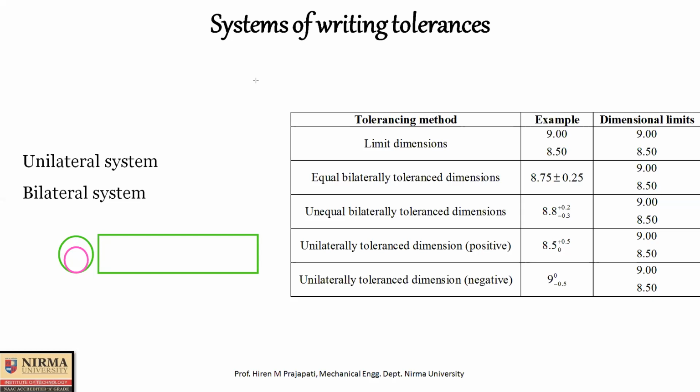Now in side view, if I take the difference between this upper limit and lower limit of the shaft, then I get this portion as my tolerance zone. Okay, so the same tolerance zone I am indicating here in side view.